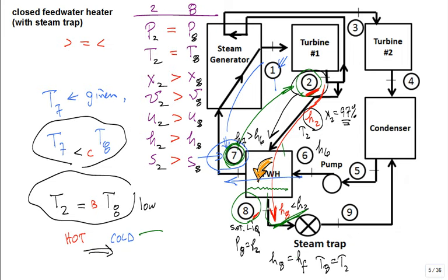So it's like a little police officer that's directing traffic, and he says, back up, hold up, until there's a pile of cars behind you, until there's a pile of sufficient liquid condensate behind you, and then I'll let some of the liquid condensate go. If there's 10 cars, they'll let 9 go, and the last car they'll say stop until there's another 10 cars piled up. Then they'll let 9 cars go, and the car wants to really go, nope, you stop. And that's what a steam trap is doing.